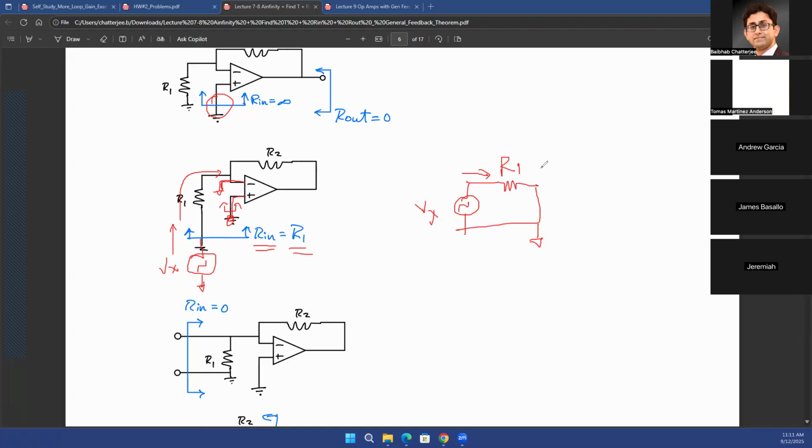You see R1, right? So you do not see an infinite... okay, now here's the fun part. At this point, you are also connecting the ideal op-amp's negative terminal, right? If you look here, the ideal op-amp's negative terminal is connected at this point. But what is the parallel combination of, which is basically infinite resistance? Looking here, you have an infinitely large resistance.